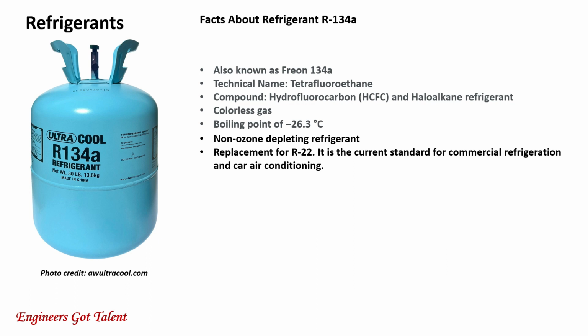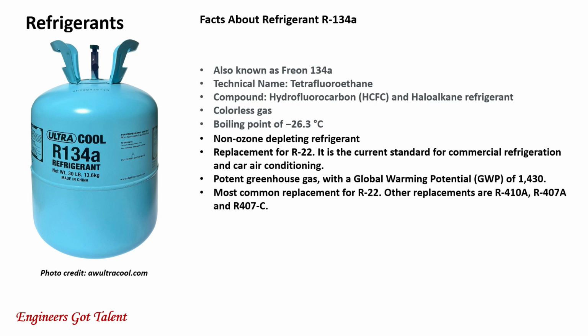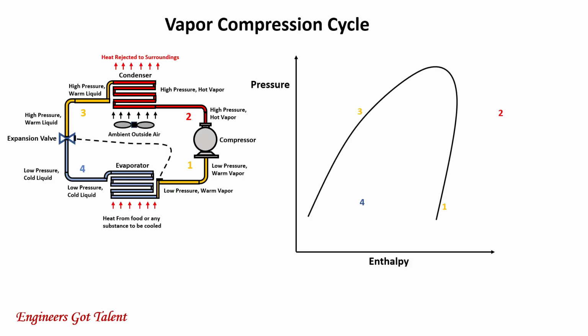It is a good replacement for R22, and it is a current standard for commercial refrigeration and car air conditioning. It is a potent greenhouse gas with a global warming potential of 1,430. It is the most common replacement for R22. Other replacements are R410A, R407A, and R407C.